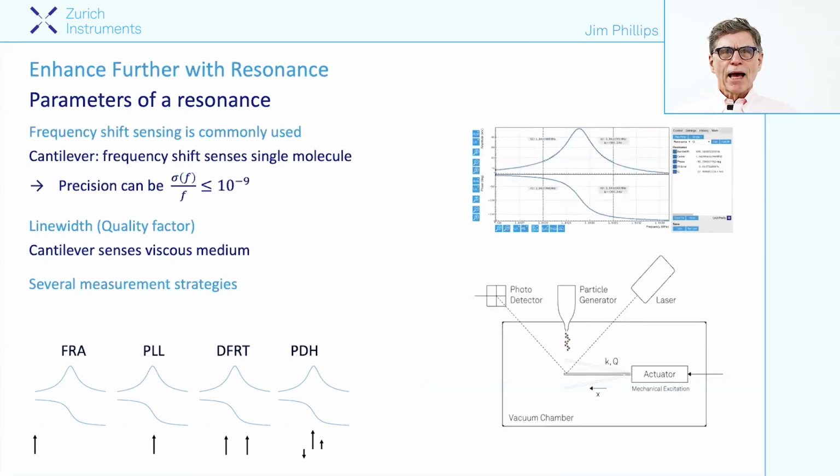So let's look a bit at what resonators can bring to this measurement. Frequency sensing is very commonly used in sensor work. With a particle dropped on a cantilever, you can measure frequency tremendously sensitively. The particle dropped on the cantilever, and Kıvanç will talk about some of these later on, can shift the frequency enough that you can measure it.